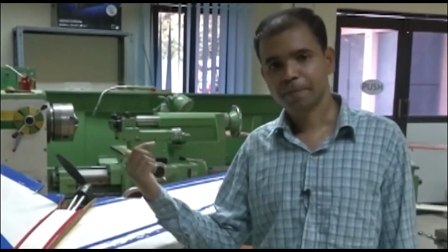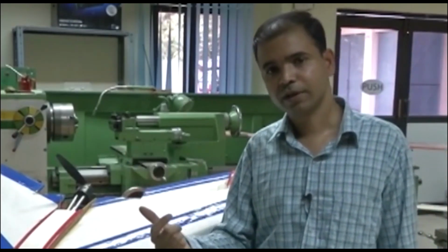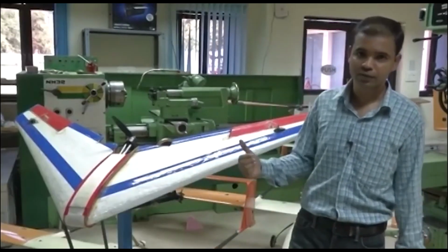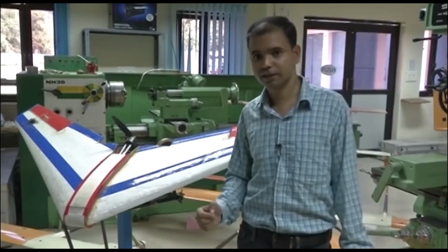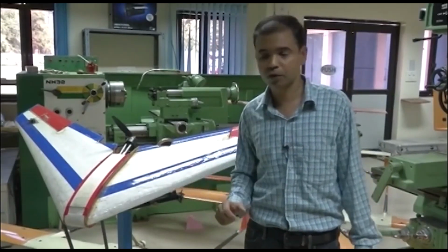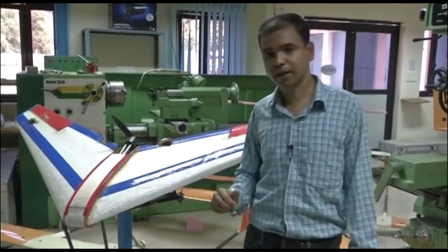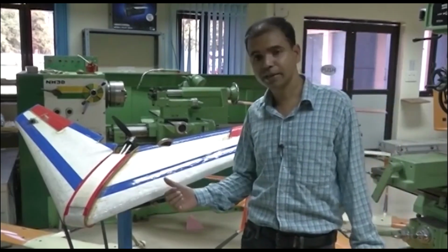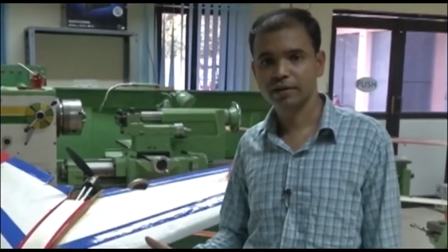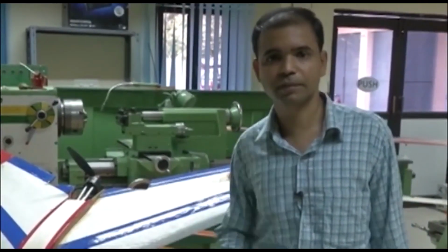We contribute a large amount of positive Cm naught, and as a result for the whole aircraft we have positive Cm naught. But here we don't have horizontal stabilizer, so we need to ensure something in this design itself so that we have positive Cm naught to trim at positive angle of attack, and that's why in flying wing we use reflexed airfoil. In reflexed airfoil we have positive Cm naught.